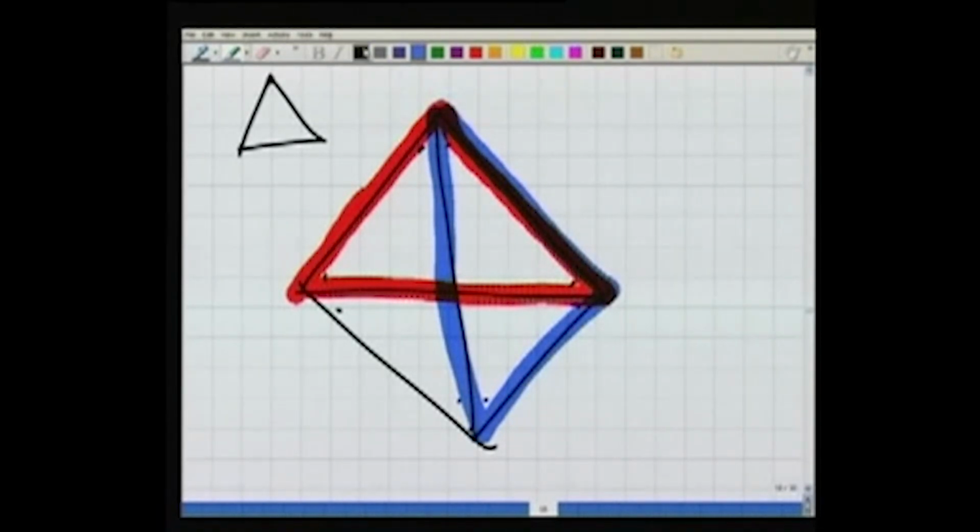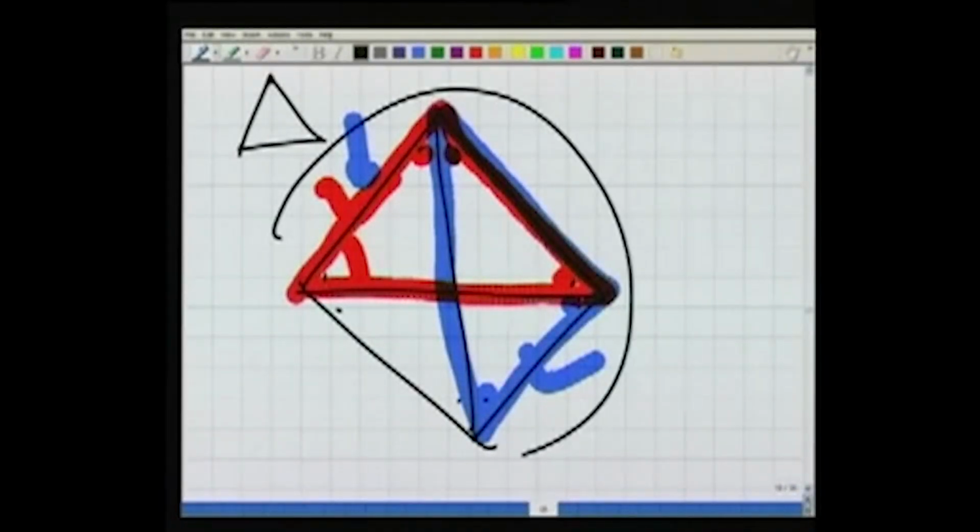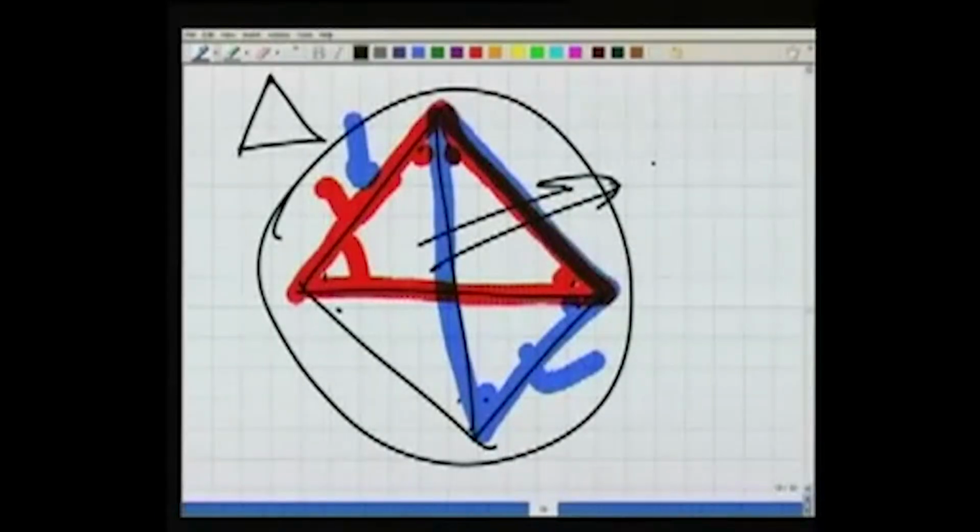If I first adjust my red triangle, I change this angle, this angle, this angle, this angle, and then I do it for the blue one. I again change this angle, now again this angle is being changed. If I adjust it for blue, the red will not be adjusted. If I adjust it for red, the blue will not be adjusted. Similarly, there are many more triangles here. So we go for a method in which we take all these observations together. We treat everything as one system, and by least squares, we adjust all these angles so that all the conditions within this figure are satisfied.